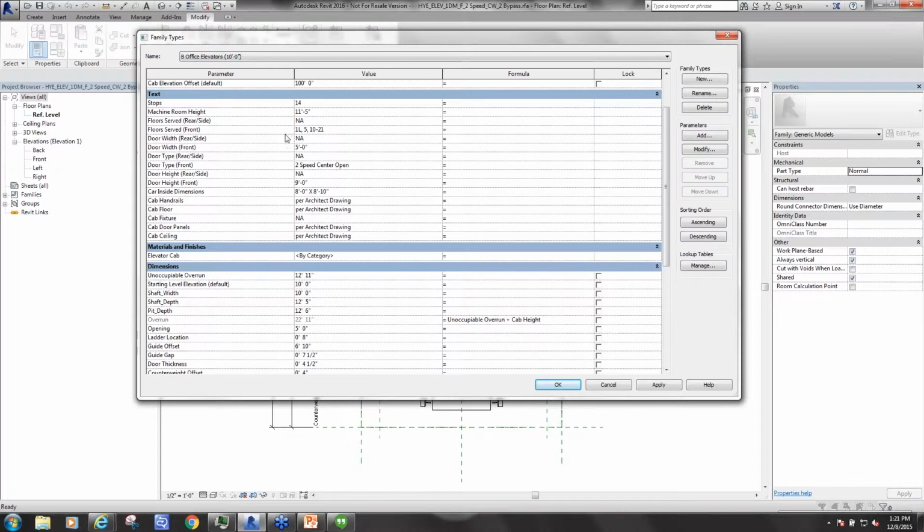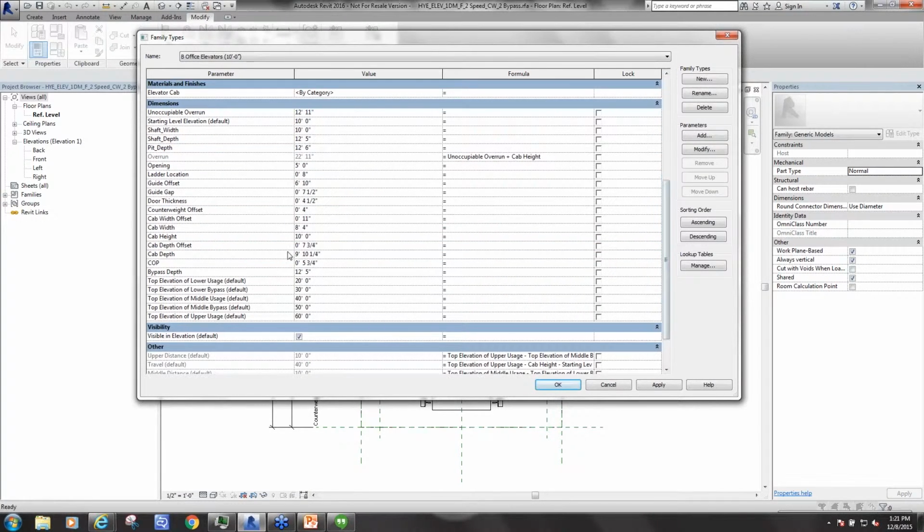So there's a series of text parameters here, and this information is coming directly from the elevator consultant. We then have all of the dimensional parameters that are coming, again, from that same cut sheet. But then several of these, of course, are changed based on our steel tolerances, and as fireproofing changes and some of our cores changed, and the actual amount that we have in our shaft.